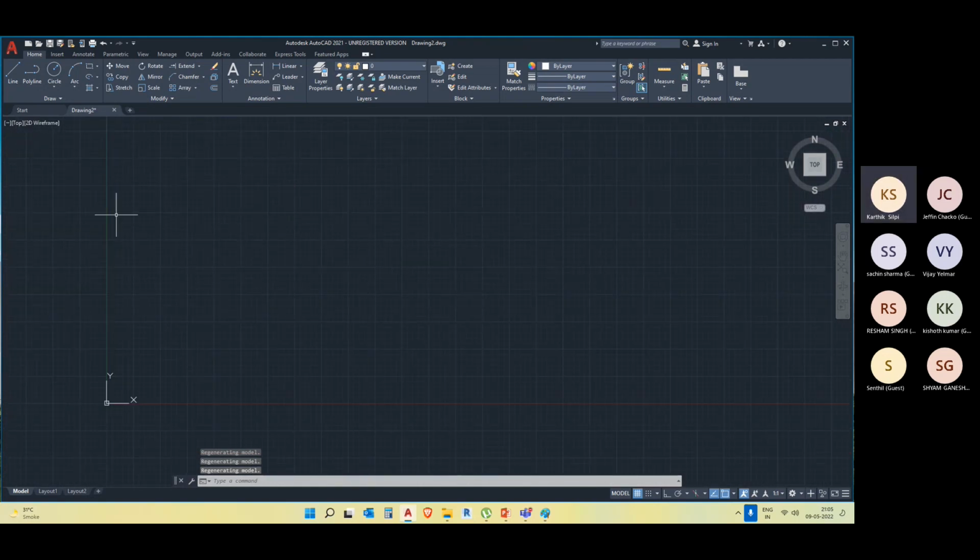After that, if you try to draw also, the system will not allow. But usually we don't recommend setting limits because we might not know until where our project goes. We can actually adjust these things after you draw. Just set the units, and then without limits also you can adjust, because anyway we are not going to print in this model space. Where do we print?